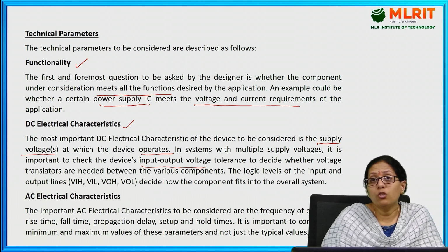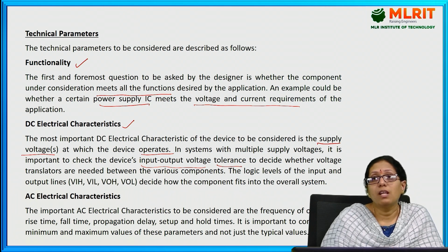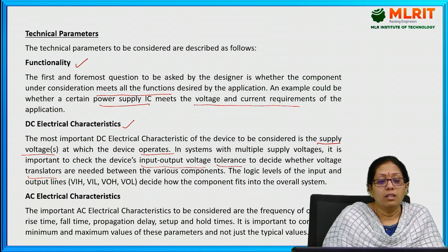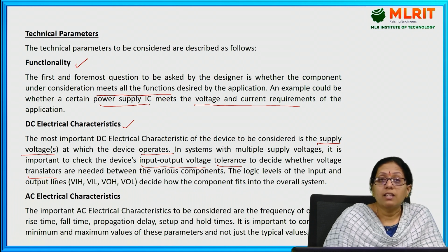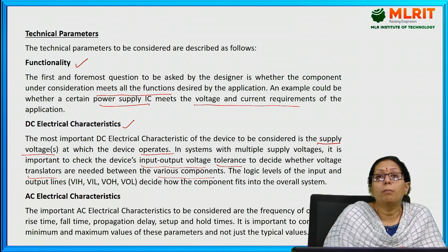It is important to check the input and output voltage tolerance level to decide whether voltage translators are needed between components. That means whether the voltage levels should be adjusted or not.